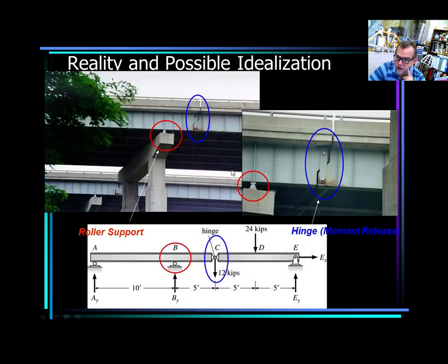And this is like a rocker on the bridge, and this is a hinge. The difference between a hinge and a pin: I always define the hinge like an internal pin. A pin helps to support the structure with respect to the base, but a hinge supports one part of the structure with respect to the other part of the structure. But there are also 2 reactions, and that's it. 2 force reactions and no moment reaction, like the pin.